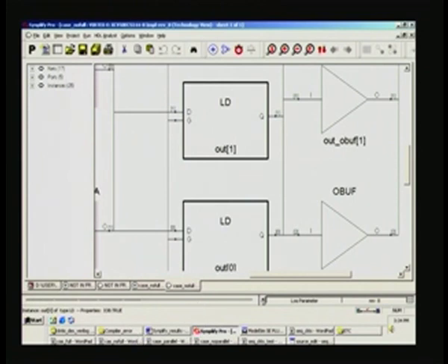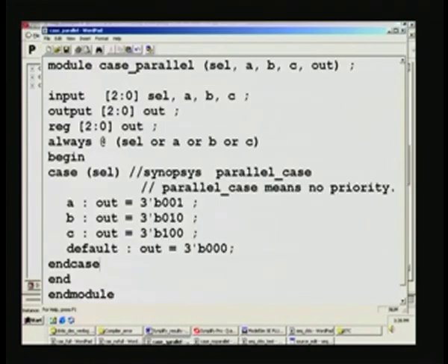We have so far seen full case and no full case, and pointed out that we can effect substantial savings just by that directive, and similarly you can have a parallel case and no parallel case. The parallel case is once again similar to that full case in the sense that case is being used, but in a slightly different sense here.